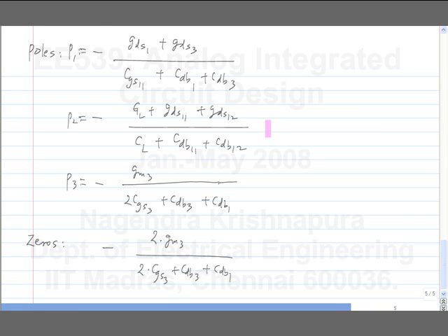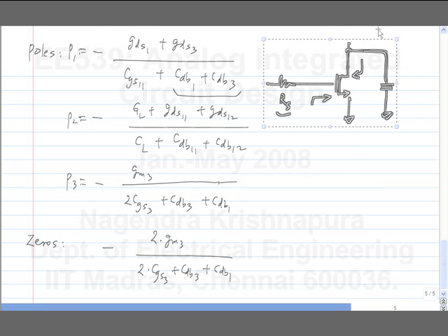So this is equivalent to, I think we have seen these two poles before, right? If you have, let's assume a transistor without CGD, you drive it with some source resistance and you have some capacitance at the output. So the input pole is related to RS and the capacitance you see here. Of course, there is some additional stuff here also because of the previous stage. And the output pole is related to the output conductance and the capacitance that you see at the output. Okay? And the two can be comparable. There is no guarantee that one will be much smaller than the other one. So we need to do something more in order to enable us to use it in a feedback loop. Okay?